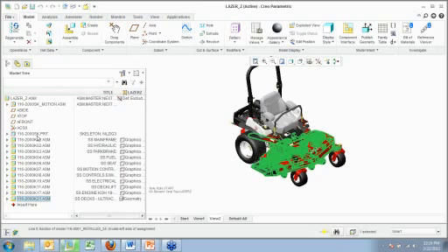So you can see these are probably every single one of these components. In this case, they've got numbers, and I'm missing some because these are different interchangeable parts, but there's 21 sub-assemblies that are able to be inserted into here, where you can have 21 different teams of people or 21 design engineers working concurrently. While one person's working on the mower deck, another person can be back here working on the fuel system. And then another person can be back here routing the hydraulic lines.